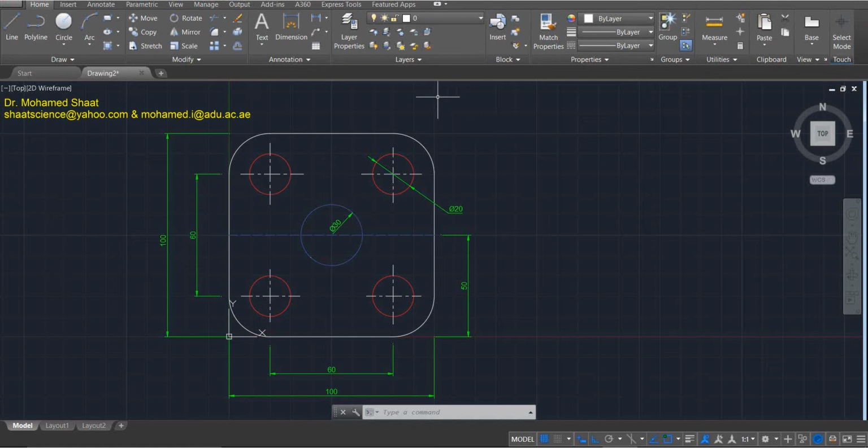So how can we manage layers? You're going to find this long panel for layers. There are lots of icons here, all of which are related somehow. The key item you use is this list, which right now has only two layers that we can use. These are the default layers, especially the first one. The first one, layer 0, we cannot remove at all. This is the first layer that we're already using.